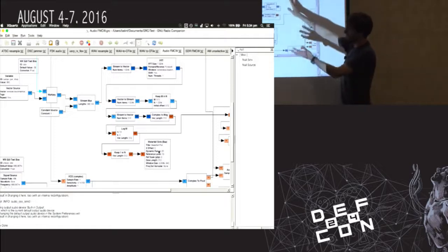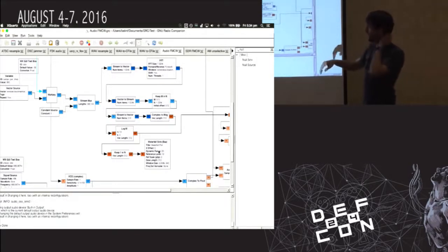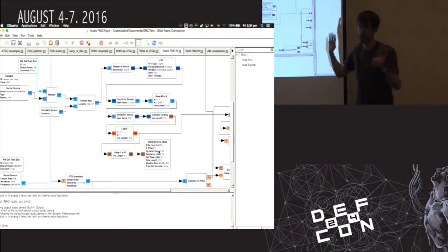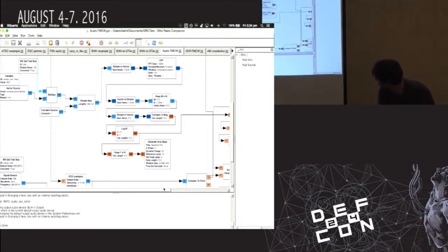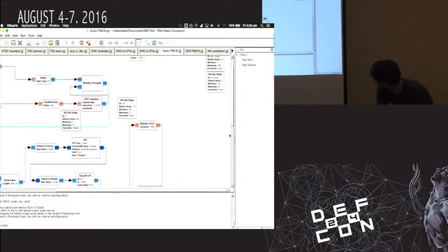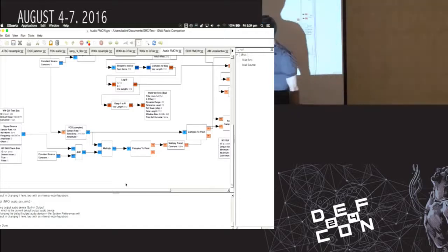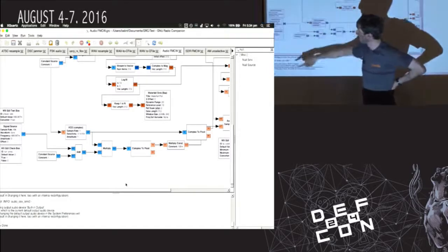So that's essentially all you're doing. You're taking the incoming signal, multiplying it by the chirp that you originally sent out, take the FFT, and then you get range information. And then what about the rest of it? What about the phasing? So I've had that checkbox there. So the checkbox is this run array. It's either a 1 or a 0.